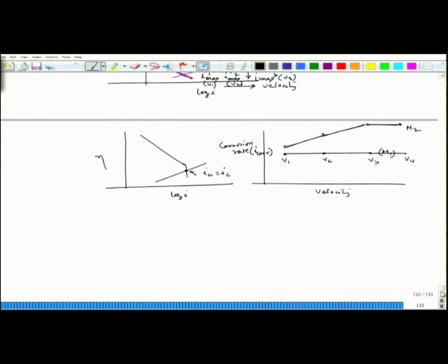Finally, we have come to the end, and as we have seen, the fundamentals of corrosion have two parts. One is definitely the Pourbaix diagram, another one is the kinetics part; one is thermodynamics, another kinetics. In case of thermodynamics, we could select areas in that potential-pH axis where we could get passivity and where we could get corrosion or immune zone. We have given some examples.